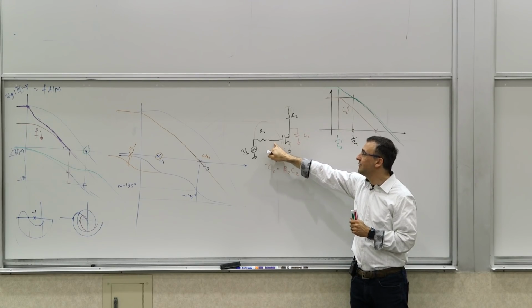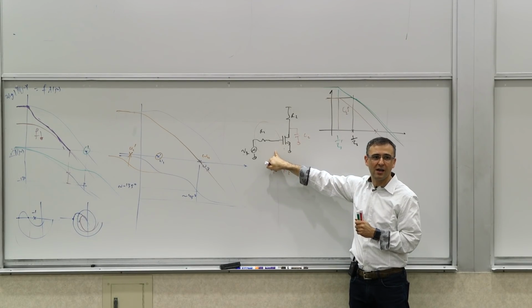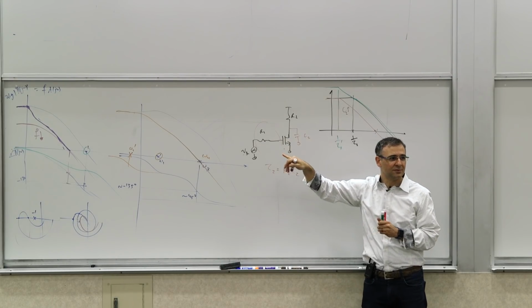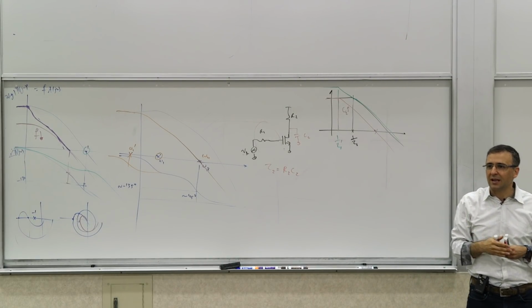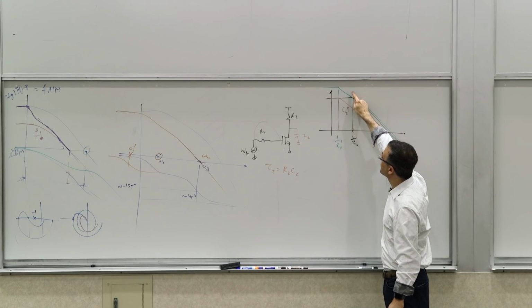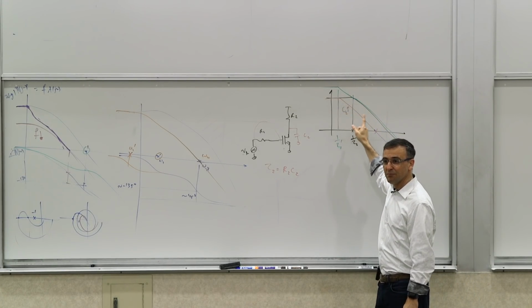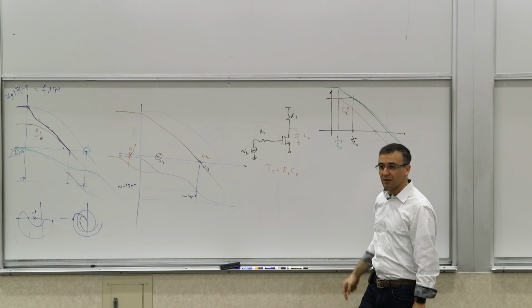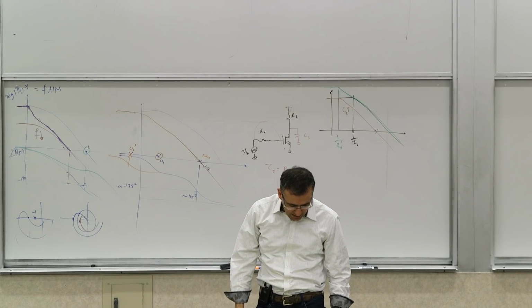I mean, if you had a voltage divider here at the input, if you had an R pi, then you lose more gain there too. So there's something else that happens. But this is something interesting to remember, that changing the capacitor and changing the resistor will have different impact on the unity gain frequency, and this is important.